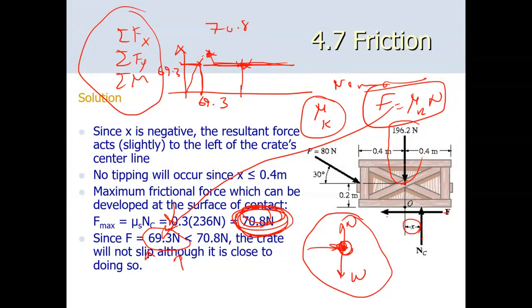Why? Because all forces then were passing through the center of gravity. But here, the forces are not concurrent as such. They're making couples, and the only way a couple can be cancelled is by another couple in the opposite direction. So this free body diagram eventually would let you have two couples which are cancelling, and eventually would make the system rotationally stable.